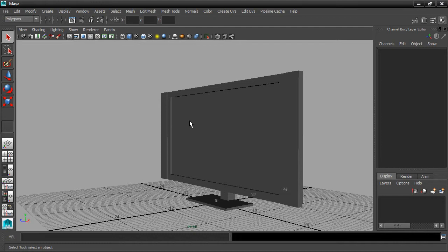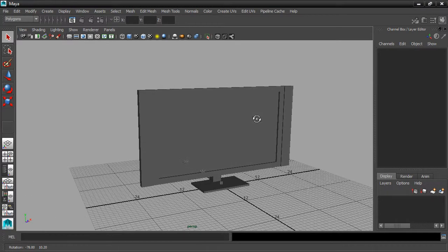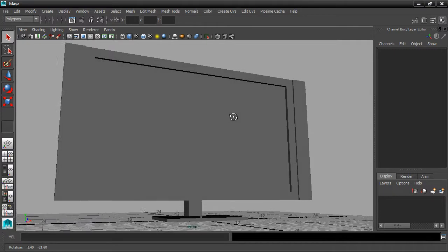In general, however, in a production pipeline, you'll probably do the UV layout before picking out the materials. It's common that the modeler will do the UV layout and then will go down the line to the next person who's going to work with shaders, and they expect the UV layout to be already done. Okay, so we're going to assign a material that's a little bit unorthodox. Usually you would do your UVs first, but it's so that we will be able to see exactly what's happening.